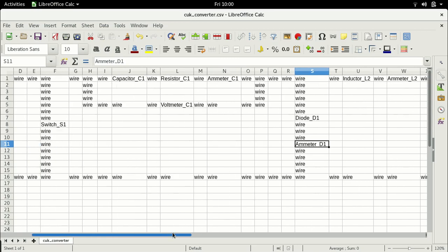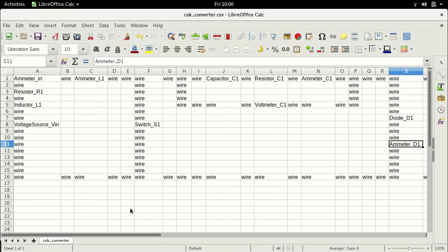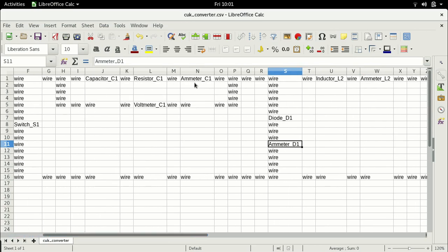So let's look at the direction. If the direction of current of the inductor is in the clockwise direction when the switch is turned on, this direction will continue to remain in this direction. So the current will flow in the right. If the current flows in the right through the capacitor, it has to flow downwards through the diode. It cannot flow anywhere else.